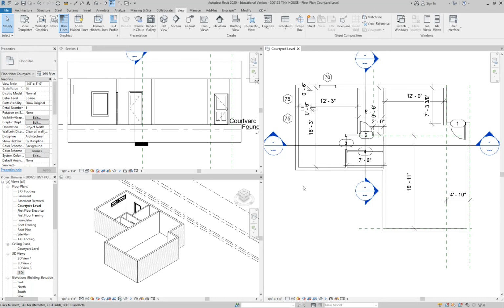All right, before we even get started, let's say you're trying to draw a roof. And let me say this part. When you're done drawing, okay, your boundary box is done, you will see 2 boxes. One of them is a big green check, and this means yes, I'm good to go. And then you will also see a red box that's like, cancel it. I did not mean to do that. You have to pick one or Revit will just sit there.